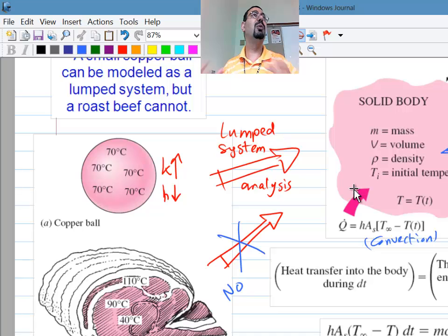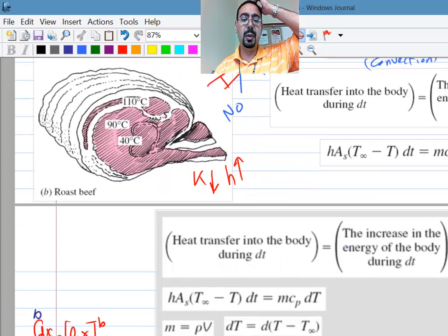It's really the first law of thermodynamics on a system: Q minus W equals delta U, right? Of course, there is no work involved, so Q equals delta U. You give me certain joules by convection, I will just take my temperature up. My internal energy, m c_v delta T, will just go up, right? All one temperature.